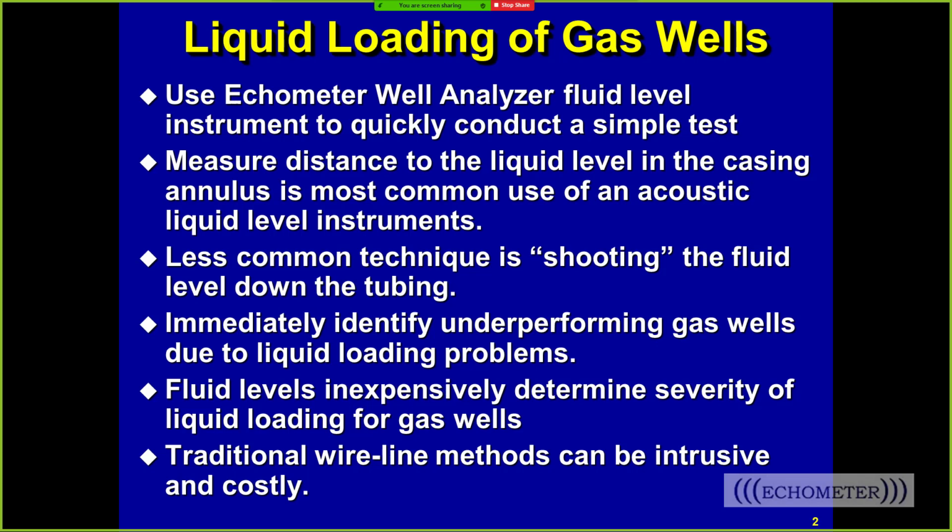We looked at quite a few wells that were sometimes plunger lifts, sometimes just gas wells that had liquid loading problems, and we realized that we could see the height of the liquid level in the tubing. That represented the back pressure on the formation when it was loaded, flowing below the critical gas rate needed to get the velocity to carry the liquid out of the well. That became an interest to me, to start doing studies on that, so we started working on fluid levels in gas wells and plunger lift.